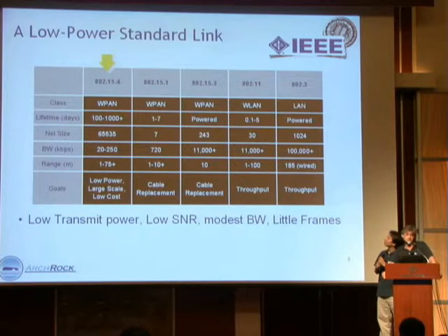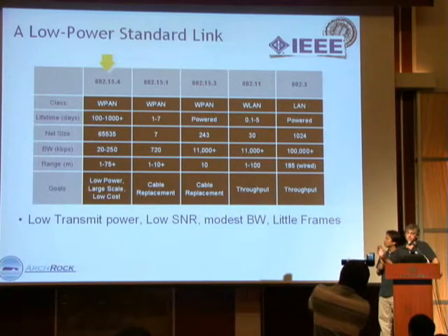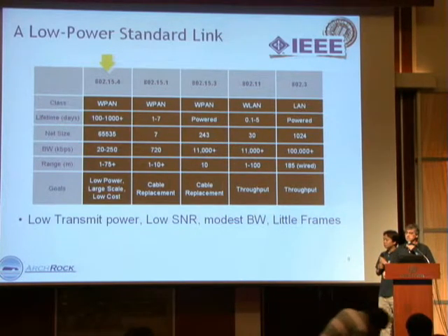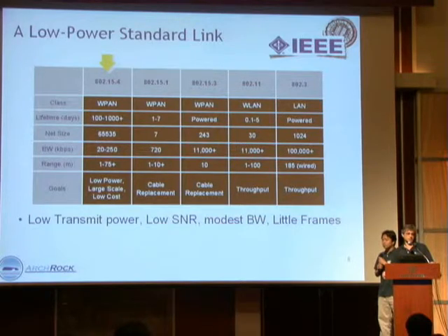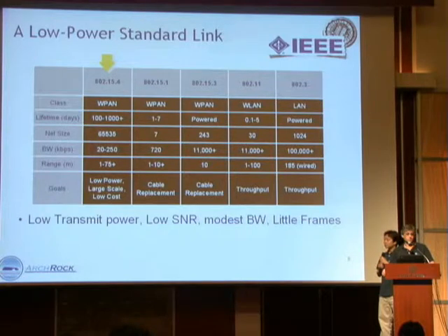On the IEEE side, it's 802.15.4. And what was so important, partly that it was designed for a large number of small devices and low power, but the presence of the standard meant many companies are producing radios that work together. So it makes sense to do a network, which until we had many different companies competing to build a better radio that worked with other radios, a network could never stitch them together. The radios are getting higher power, higher reliability. Sometimes this is called the Zigbee radio, but it's the 15.4 part that is what's so critical. In fact, we only use a small part of the 15.4 MAC.